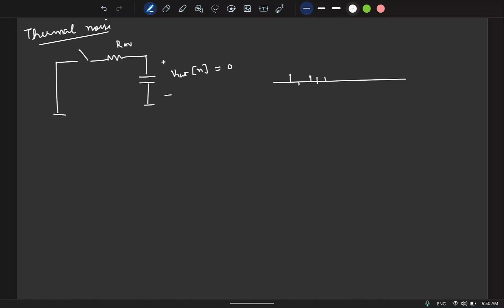Thermal noise. Okay. And this is basically due to the random fluctuations of the electrons in the resistor. And usually to model this noise, what we do is this: we take this noisy resistor. We'll assume that the resistor is noiseless and the culprit is some other hypothetical voltage source in series. So this is noiseless. Why do you consider this term? Is it not very small? How small is again dependent, right? Small means relative to what? So this is the point I'm making. Let's see, hold on. Because we never considered this thermal noise anywhere, right? In analog circuit design, we never considered.